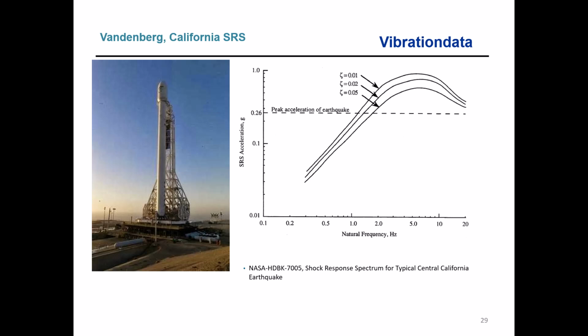And once we get above 1 hertz or so, there's this potential for dynamic amplification, as shown by those 3 curves there. So that's what mechanical structures do in certain cases: they amplify energy, so response can be greater by several times the peak input acceleration. Now, eventually, at higher frequencies, all those curves would converge to peak ground acceleration.